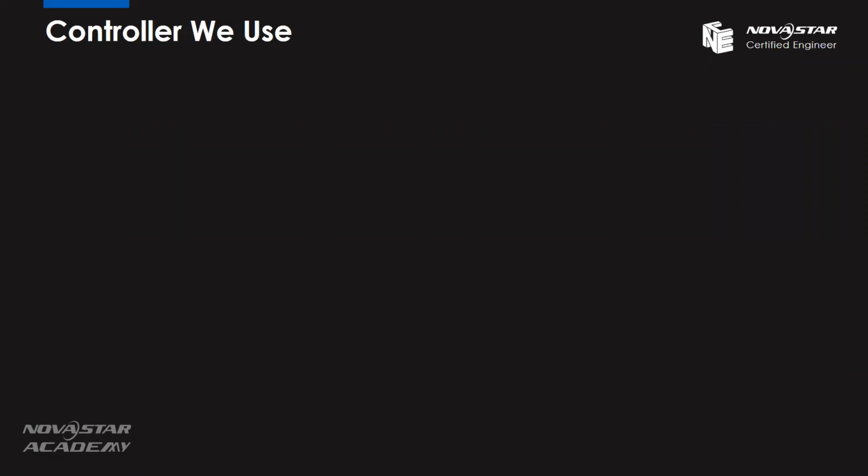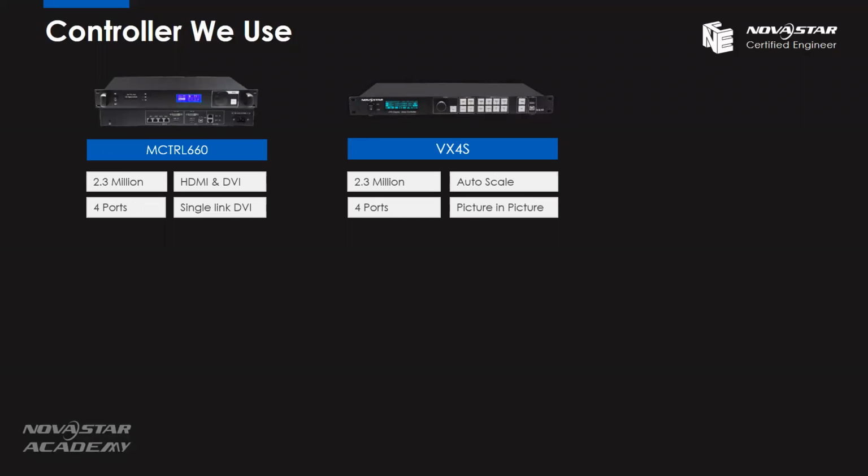Okay, now let's have a review of the controllers we use today. The first: when we use the 1080p level to splice the 4K, we use the M-Control 660 and a VX4S. Even though the M-Control 660 was released on the market a long time ago, it is still popular. I think the reason is the front panel. Because we have the front panel and a knob button, we can realize quick configuration. And it supports 2.3 million pixels, and the video sources are HDMI and single-link DVI.